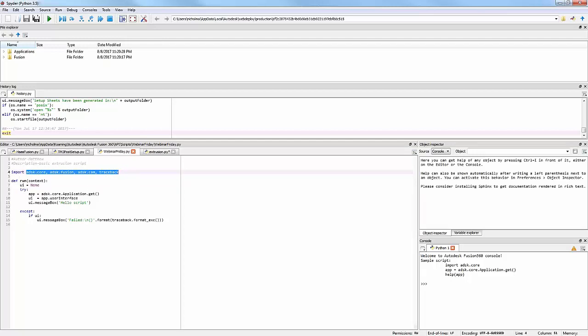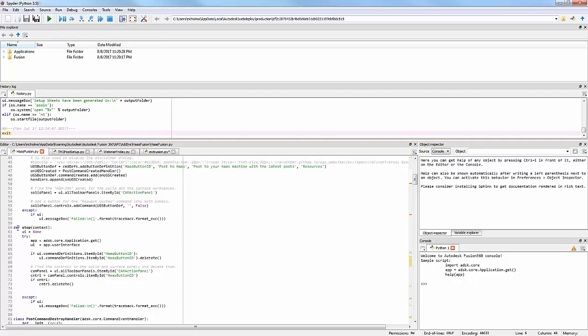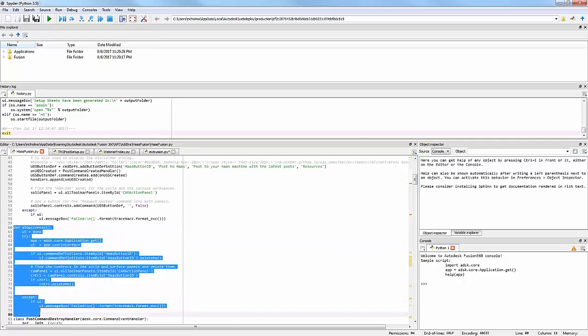Since we did the script, you'll see I've got the function run here labeled with the def, and then context. Whatever is in here is what it's going to run. However, I don't have a stop definition here, because as soon as I hit OK on the dialog, it automatically kills the script. To show that as well, since this is an add-in, I've got the stop as well. That's one of the other differentiators between the script and the add-in.